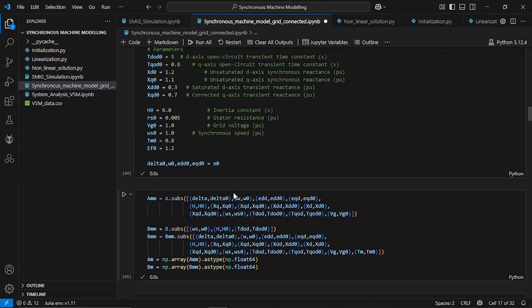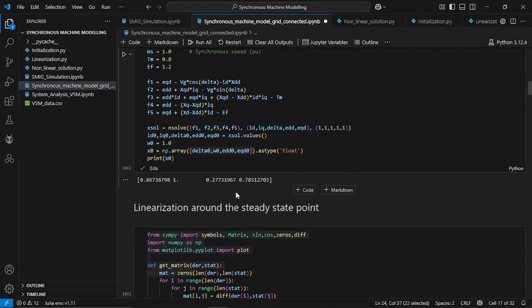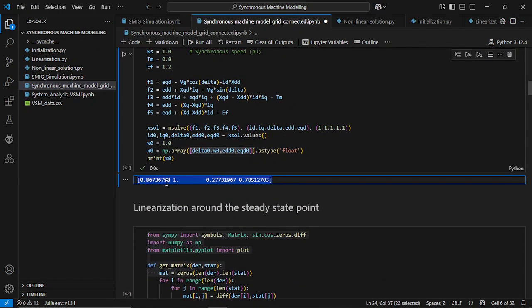Around that equilibrium point, we will linearize the system. We'll develop the linear model, and we'll solve the linear model, or we'll use modern control theory, that is ABCD. We develop the ABCD matrix and determine the eigenvalues, or design some kind of control system, like developing the governors, designing the automatic voltage regulator, and so on.